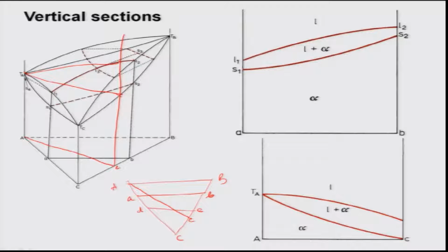Thus it is possible to show these different regions just like a binary phase diagram, but here you see one end of these curves is joined, the other end is open. That is because it starts from an A-rich end and ends at an alloy on the BC side, that is, an alloy consisting of B and C elements, with no A. As I told you, compositions sitting on the sides of the triangle tell you that they are binaries, okay. Very clearly I cannot draw tie lines here also and do calculations; these are not allowed at all.